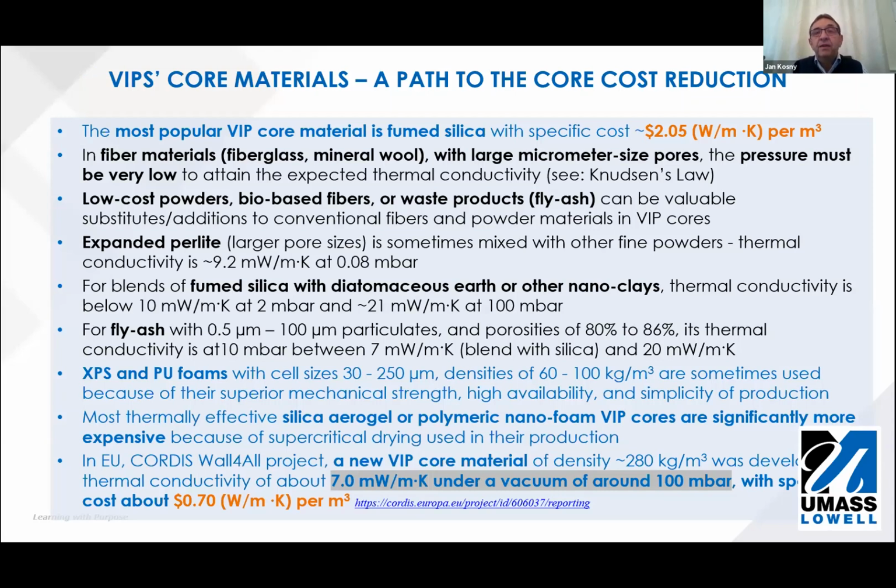There are many different core materials in use right now, with fumed silica being probably number one and most common. The reason is that fumed silica powder is giving very low size pores, and as I said before, they afford a very low level of thermal conductivity with reasonable levels of vacuum.